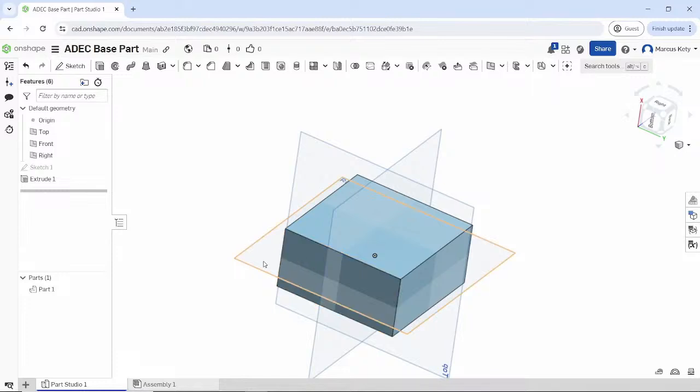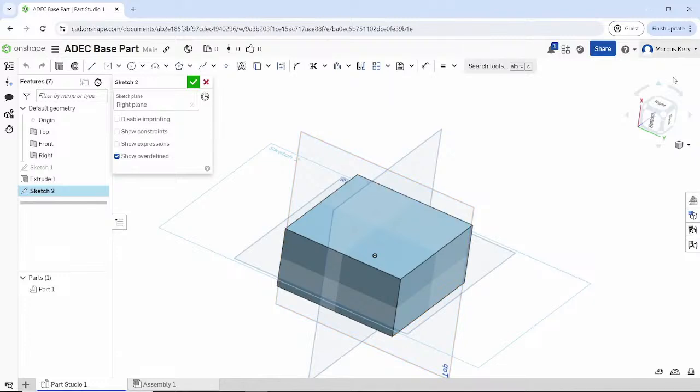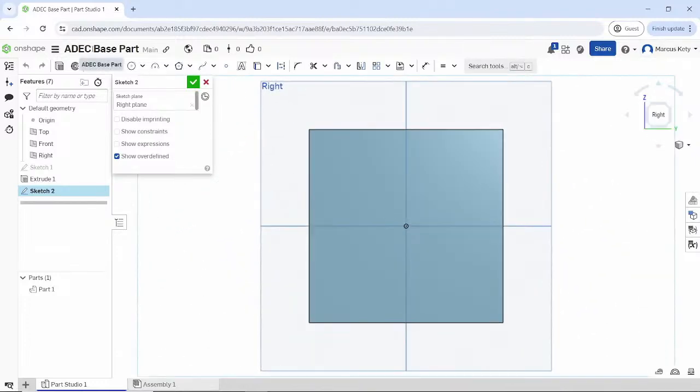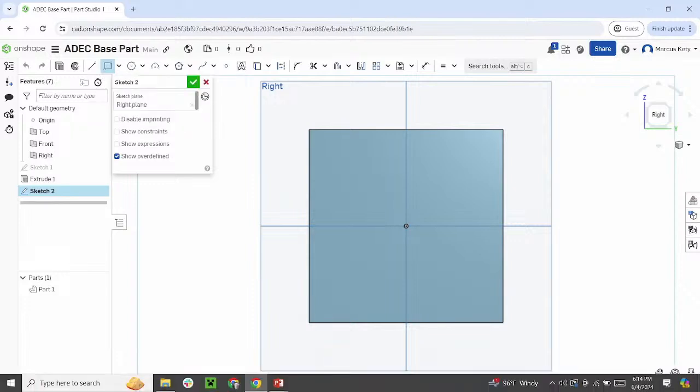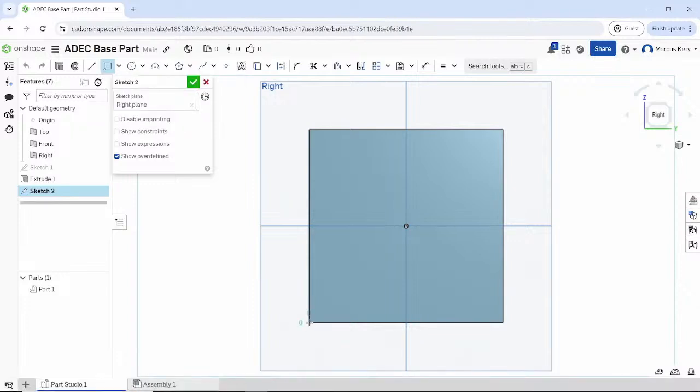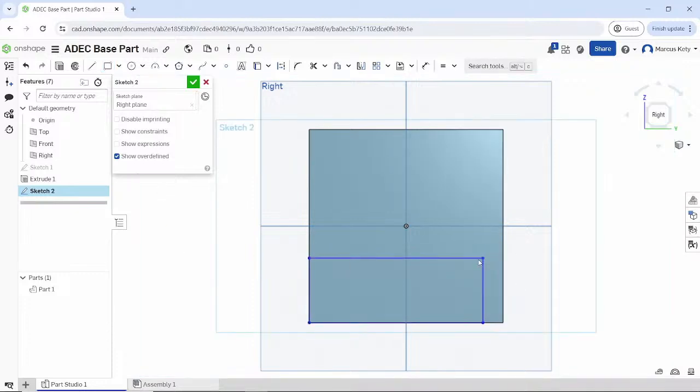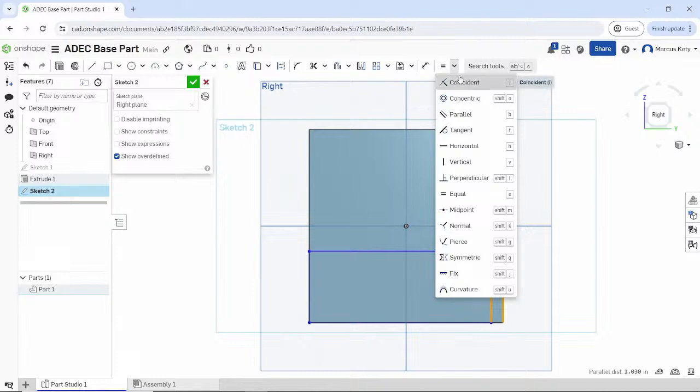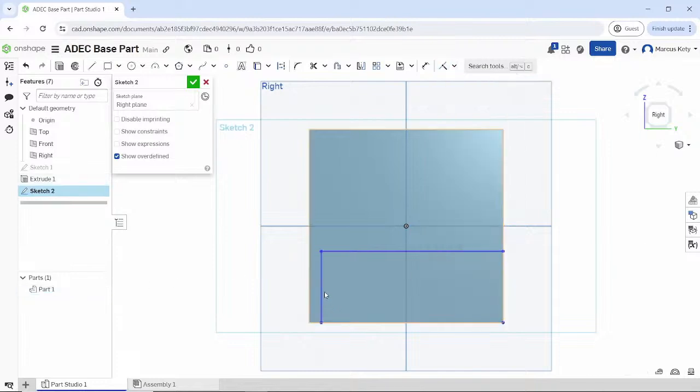If I want something to be symmetric across the middle, say I want to make this a C shape instead, I can make a new sketch looking at the right plane, do a 2-point rectangle, go from the bottom edge to this edge here, and you'll see it is also not fully defined. So I can select that edge, this edge, and make them coincide.